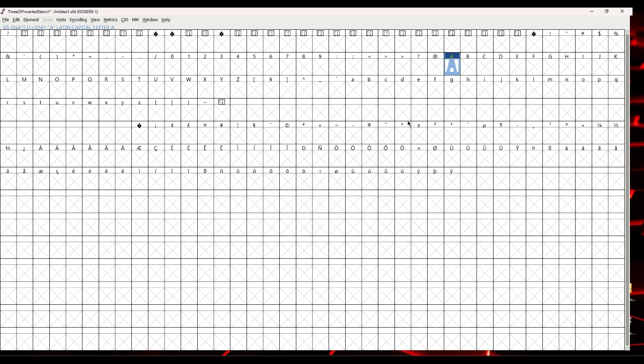Now it has to be more than 0, because if it's less than 0, I've tested this, the letters will overlap in Fusion. And when the letters overlap in Fusion, Fusion doesn't know what to do about that when you try to cut things out, and it'll just give you an error, right? So these letters are not overlapping, but they're separated by such a small distance that when you go to slice it and 3D print it, the line that's left over is so small that it won't get printed.